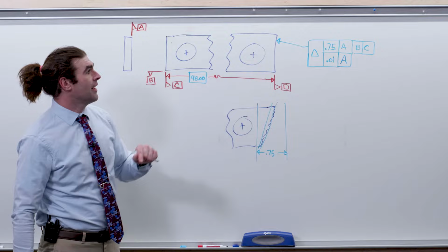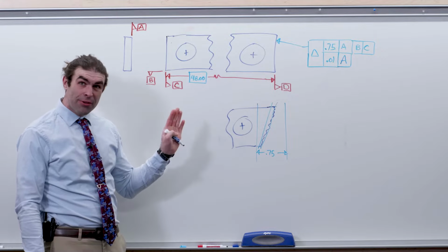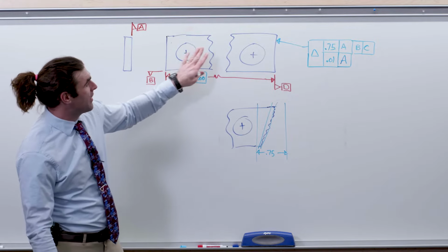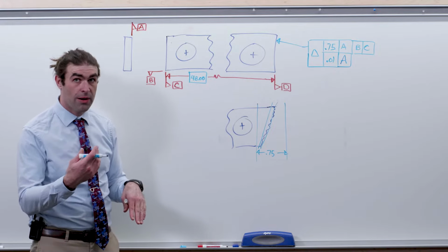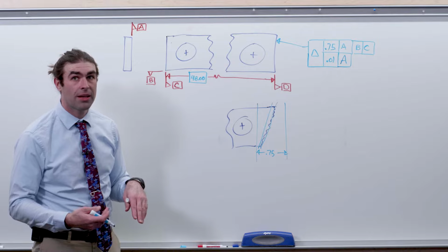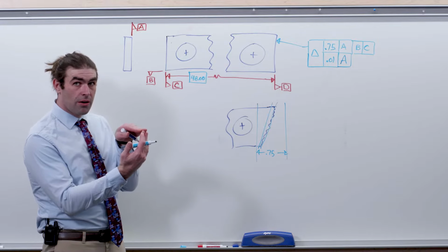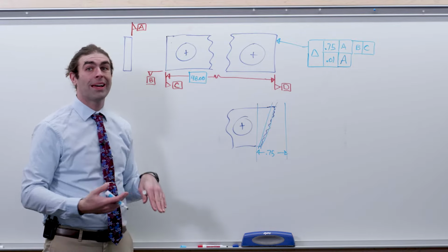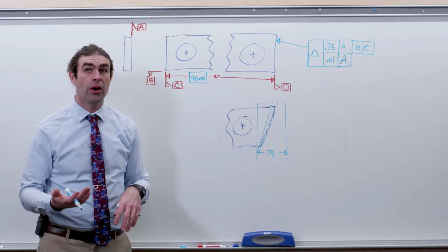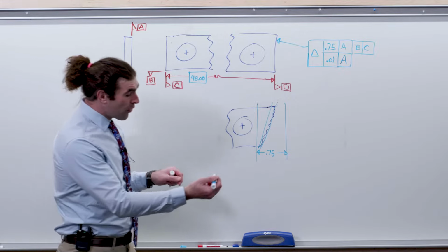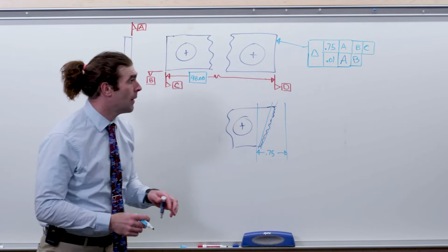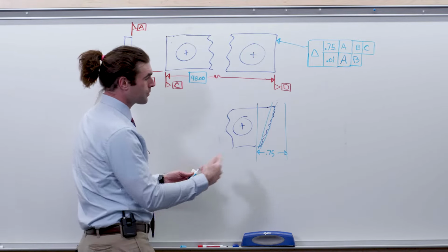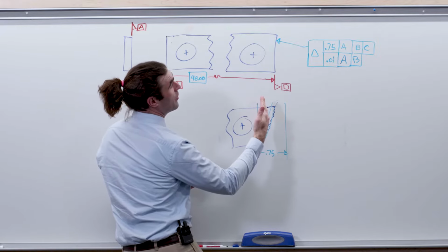We're going to add datum A. Now it's difficult to see here, because datum A is that large surface, but you could potentially, without referencing datum A in the second segment, even the thin portion of the part could be out by 3/4 of an inch, which isn't what we want. So I'm going to skip ahead to datum B here. What that's going to do is snap this into shape.